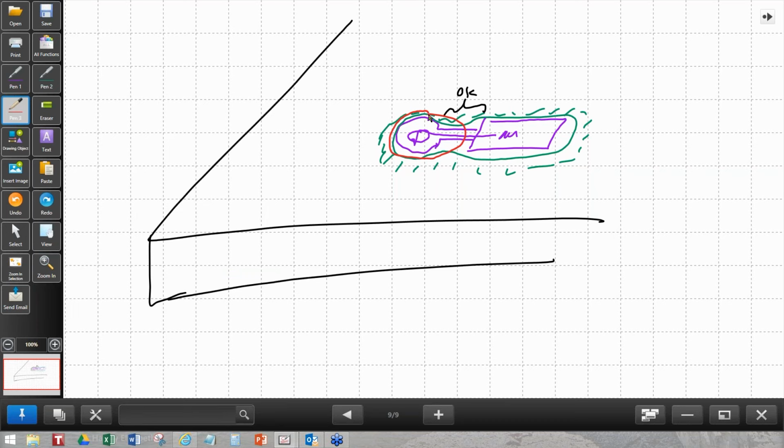But again, this would be after it's fabricated. If after the fact means after the board is completely assembled, then you have another problem. If the board has already been assembled, then the solder that was under this has already gone down the hole. Therefore, this joint is starved. Therefore, you can't fix that outside of reworking it.